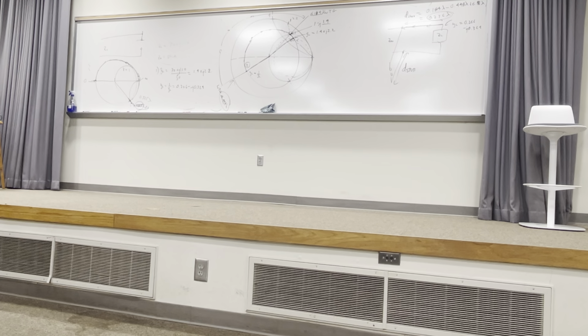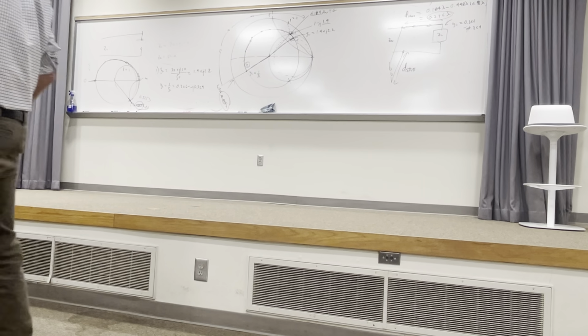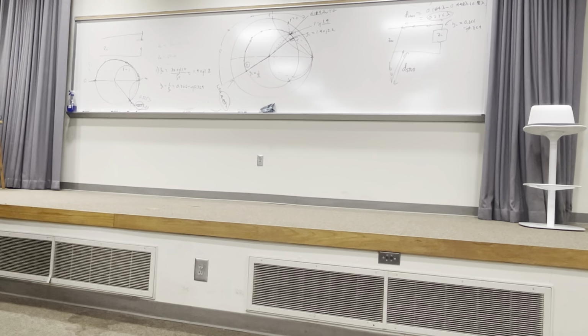Okay. All right, now I'm going to level with you with this. I have taught this course many times. This is the biggest common mistake. You will look at the original Smith chart where you charted the 2 points, and you'll take that point because it's the conjugate value, the J 1.8, or 1.9, you want to get rid of, and you go there and you get the wrong answer. I'm just telling you, I know this. You have to be focused when you do it. And it's easy mistakes like this that cost you big points.